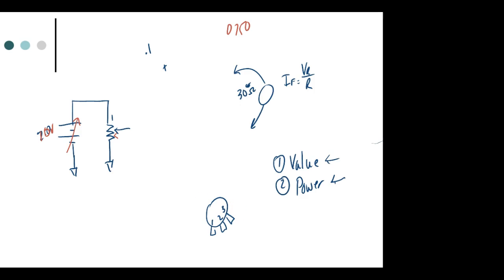1 and 3 you can interchange. It doesn't make any difference. There's a standard, but I don't have it in my head. It determines which direction you turn it. If I hook it up one way, I might turn it clockwise for the voltage to go down. If I hook it up the other way, clockwise causes it to go up, right?